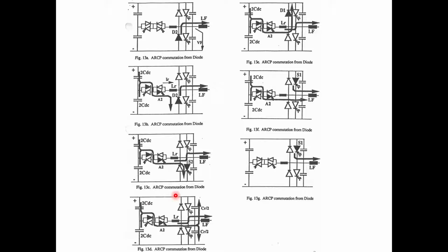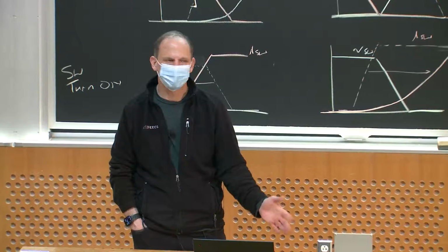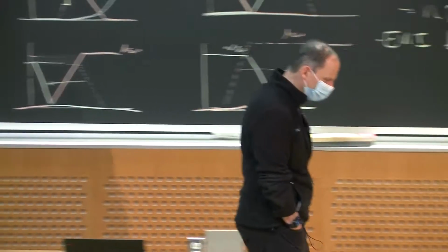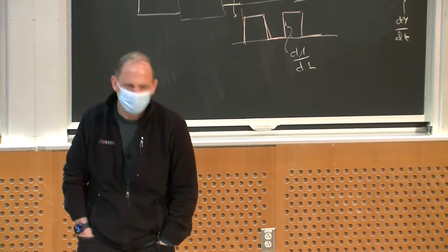And the things you get are reduced switching loss in the main devices for a small extra auxiliary circuit, which is also soft switched. And you get, this is another set of commutations going the other way. You get, because of the snubber capacitors, reduced dV/dt on the switching transition, and hence reduced EMI driving your motor. So that is a lightning introduction to soft switching and some of its benefits, and just an introduction to some of the ways you might go about it.